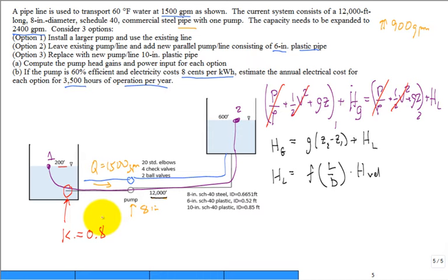So if you look at this on page 18 of the textbook, for a pipe entrance sharp edge, they have a K of 0.78. So I know that in our table here, I think we have some other Ks, or you could look in your other fluids textbook. There is some variation, 20% at least, in some of these loss coefficients. But when in doubt, just go to a standard like that.